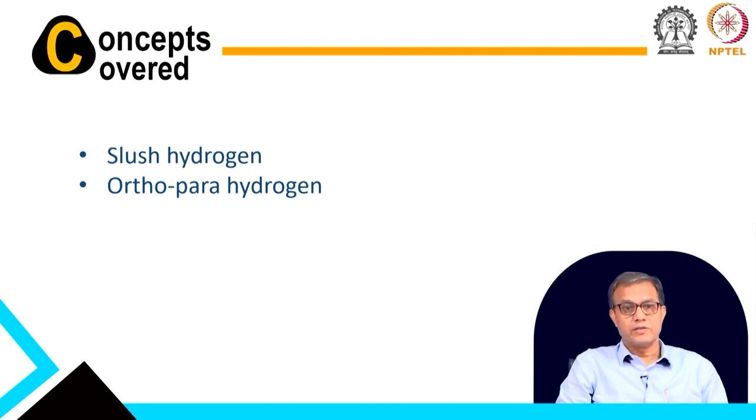So, its density in the gaseous form is very low. So, we have to densify it while storing it, and one of the storage means, as we have learned, is that we can compress it, and another form of storage is liquid hydrogen. Liquid hydrogen is denser than the compressed hydrogen.